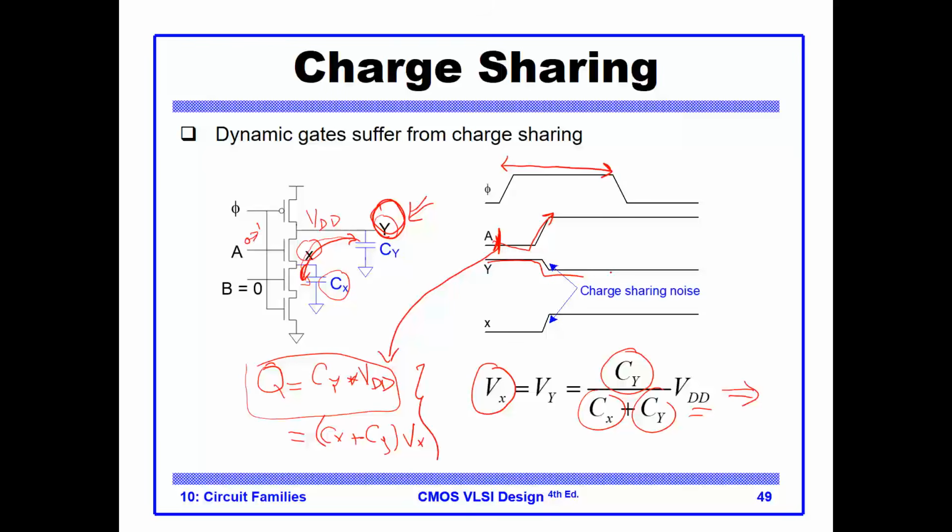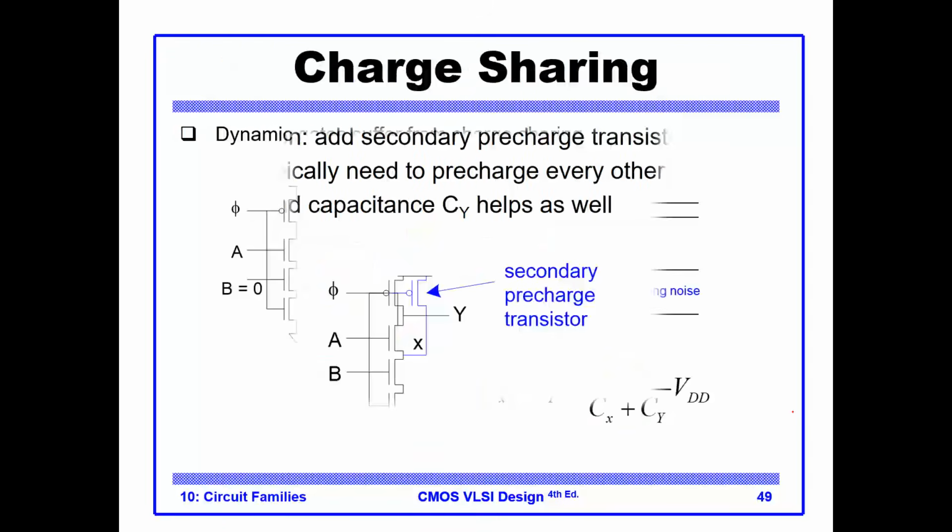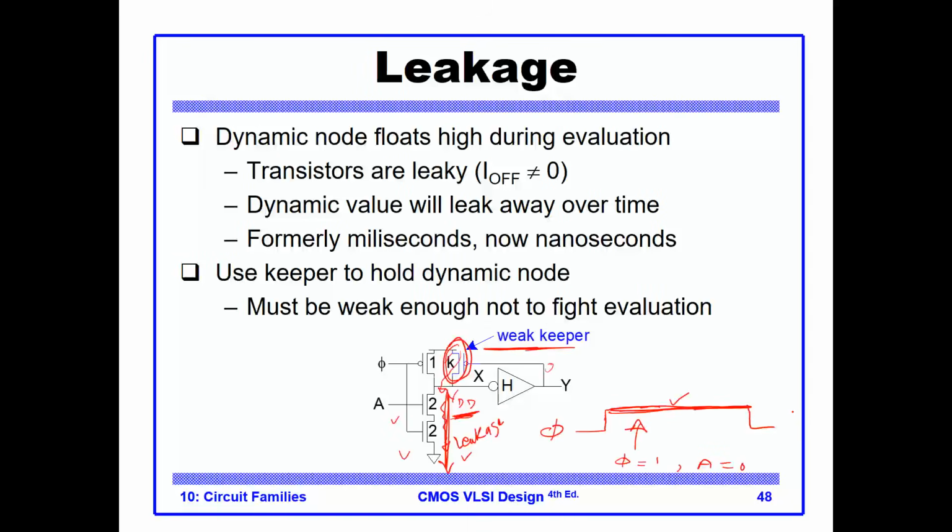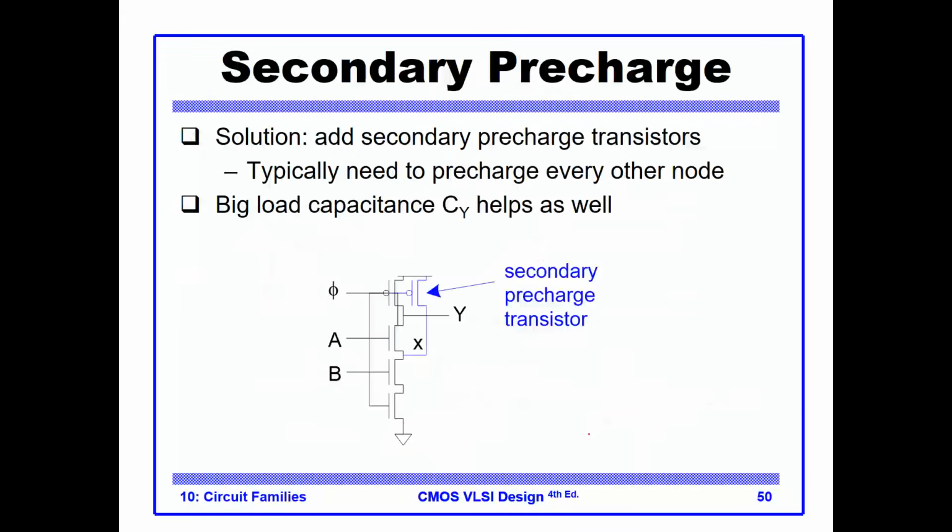So we need to prevent this, and one way to prevent it is to pre-charge this internal node. And with this pre-charging, remember we said that the initial number of charges is Cy times VDD, and now we will add also Cx, so it will be initialized to VDD. When this turns on later, we will not have any drop of voltage at the Dy.